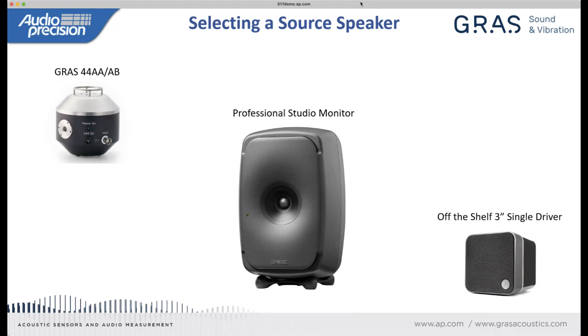As far as just using a regular speaker, which is a completely valid choice, the main issue that controls is the frequency range of interest and the sound pressure level that you're looking to achieve. By the frequency range of interest, I mean, if you want to measure the frequency response of a microphone from 20 hertz to 20 kilohertz, well, it can be equalized, but you can't equalize from 0.